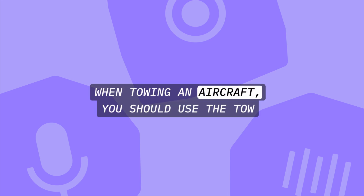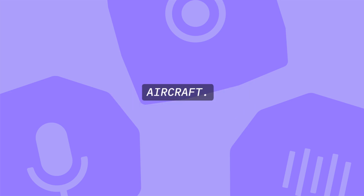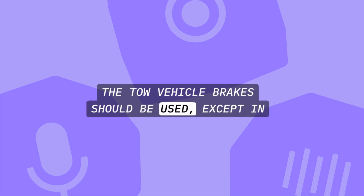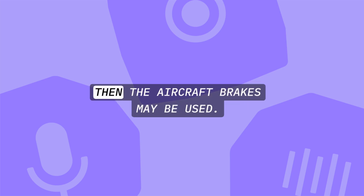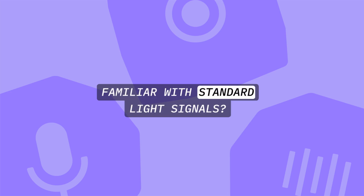When towing an aircraft, should you use the tow vehicle or aircraft brakes to stop the aircraft? The tow vehicle brakes should be used, except in an emergency. Then the aircraft brakes may be used. Why should an aircraft technician become familiar with standard light signals?